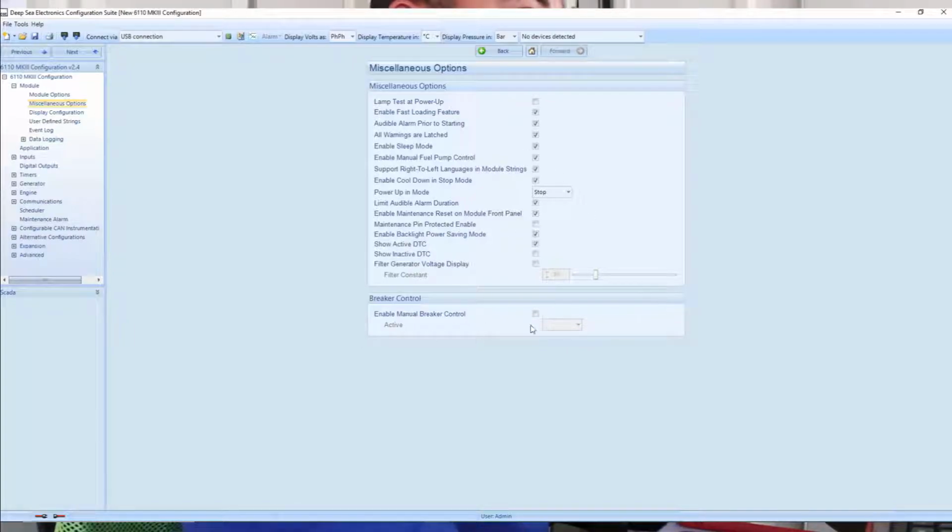Okay, so enable breaker control. You have to select on input or always. If you select always, you have a pause button there, I will show you, and you're supposed to have a motorized breaker in order to command that. For example, no need to manually turn on the breaker, you just press the button, if you enable this one.